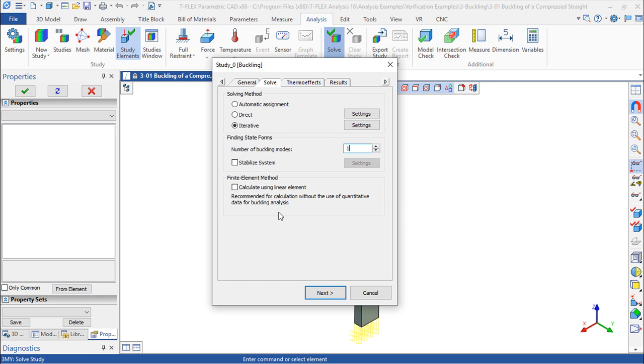This in fact facilitates a much faster calculation for having an estimation of the buckling mode amplitudes of the structure that we have in presence. So for easier and small element structures, we can leave these not activated. If we are in presence of big things, complex, maybe we can save some time using this method here.